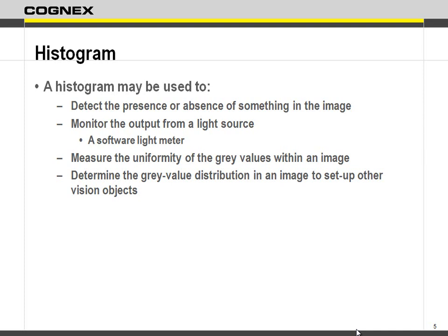Can the vision tools adjust for the lighting? Oh, you could potentially feed that back to let the vision tools adjust for it, but this one's just letting the PLC know your light's getting low, so it doesn't get so low that it starts affecting the vision tool, saying, whoa, you're not giving me enough contrast. But yes, you could feed that value back for a threshold. You could feed it back so maybe it increases the brightness level. Now, if your light's really degrading, you've got to change it. But you can do some type of arbitrary threshold point and feed it back.